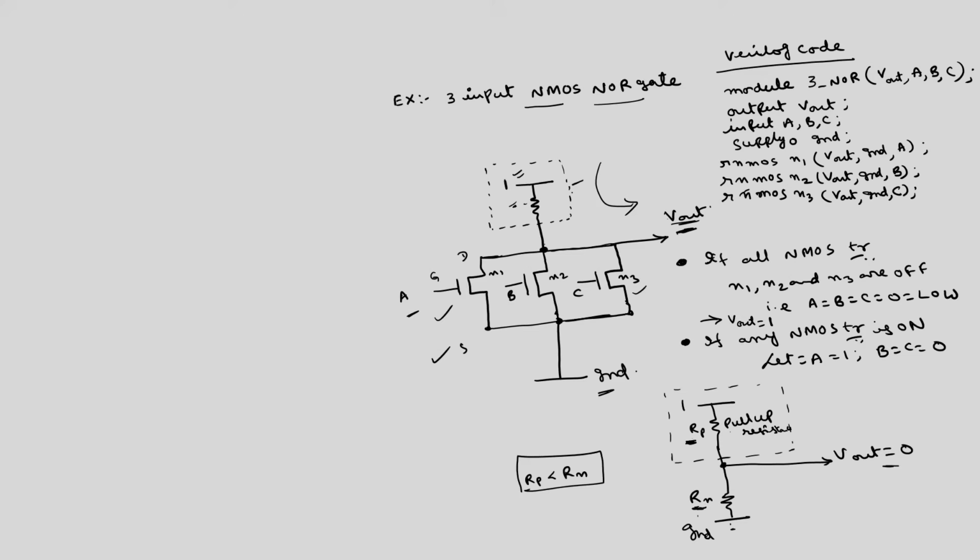Then the output will be pull up, out. So, this out will be 1 if all these 3 inputs are zeros, otherwise the output will be 0. End module. In a similar manner you can explain about pull down also. I have explained about the pull up with example. In a similar manner we can use pull down also, pull down out. So, these are the other 2 primitives.